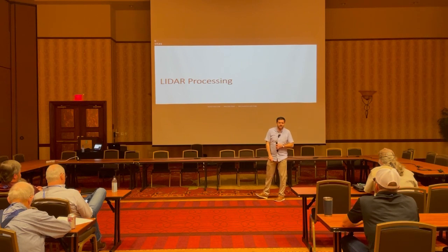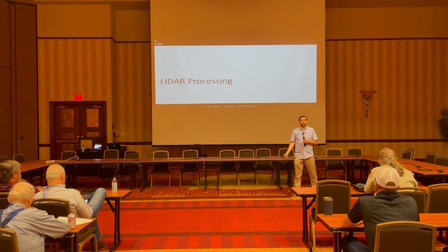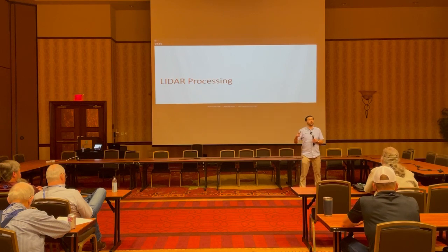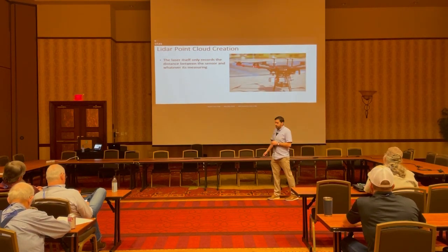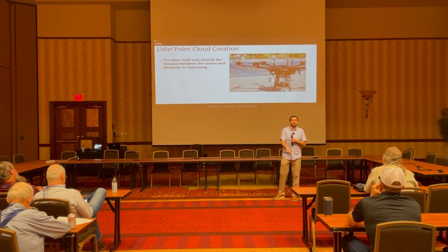So let's talk about LiDAR processing now, because again, even though photogrammetry still makes up the bulk of drone surveying, LiDAR processing is what most people are interested in because it is the new thing, and also because there's a lot more questions about LiDAR processing. Well, for starters, you need to actually turn the LiDAR data into a point cloud.